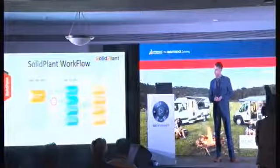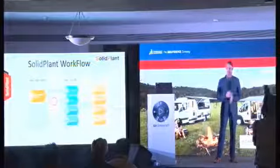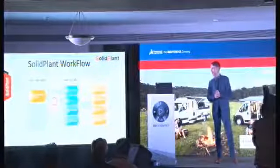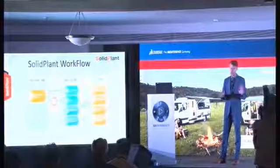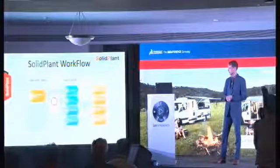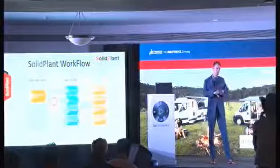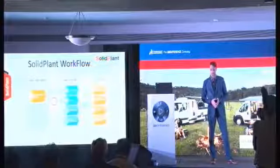And we also have output documents, which is very important in plant design, especially isometric drawings. We have an industry standard isometrics called Isogen, which is now the industry standard. It's already there. You know, everything is included. You don't have to buy any separate module. It's already there. Next to that, we have automatic generation of your general arrangement drawing and bill of material. What's very important is all these drawings are just generated automatically, which will save you a lot of time.